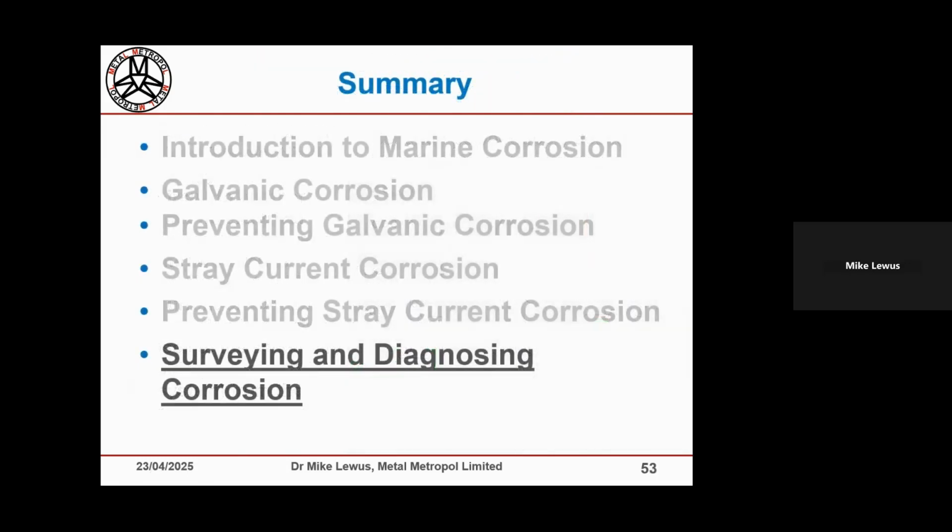It's probably worth mentioning a couple of other devices that are sometimes used. Actually, one that's always used: ground fault circuit interrupters or circuit breakers. That's a device that checks that the current flowing into the live and neutral are similar. If they're different, it can be because of the presence of a stray current. So circuit interrupters are commonly used.